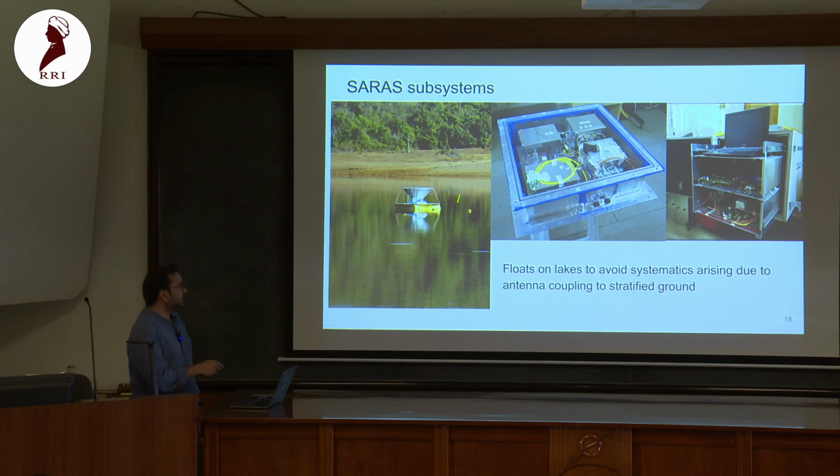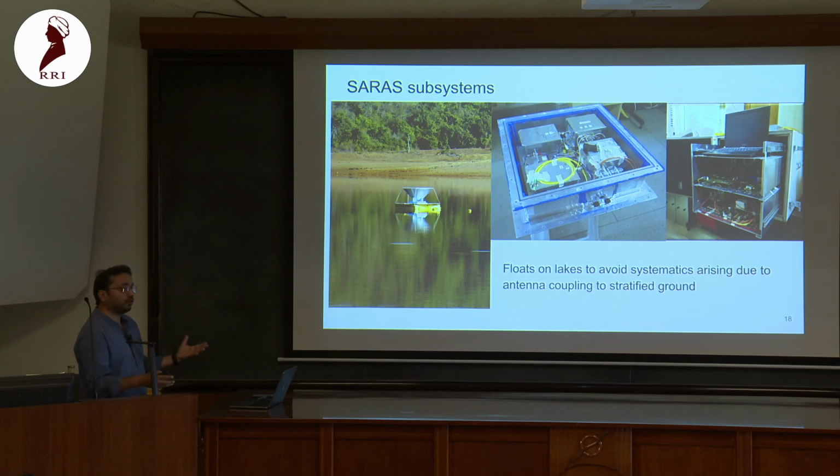So it's basically, as I said, there is this antenna and an analog receiver that sits just beneath it. And one thing that makes it very non-conventional is the observing medium. It floats on water. That's simply because on ground, you also have stratification. So again, it ties up with the standing waves. You have different reflections at different strata of the ground. And that is very hard to model unless we really have the huge profile along with their conductivities and permittivities. Challenging task, especially because we are talking about wavelengths of a few meters here. While water is a very uniform medium, and there are only two length scales in this. One is the depth and one is the shore. So this is fairly easy to both measure and model in electromagnetic software.